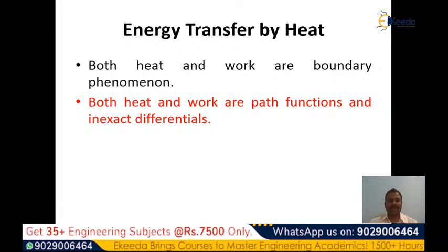Like that, heat also: the magnitude of heat involved in change of state from state point 1 to state point 2 depends on the path that is followed, as the magnitude of heat transferred is different as it follows different paths. So both heat and work are path functions, and since they are path functions, they are inexact differentials.